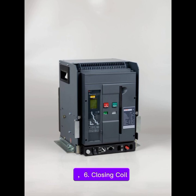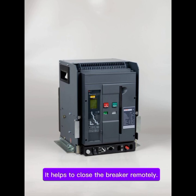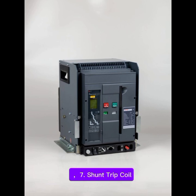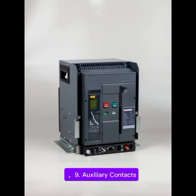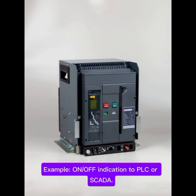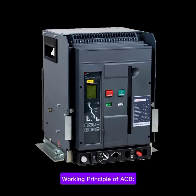6. Closing coil. It helps to close the breaker remotely. 7. Shunt trip coil, used for remote tripping. 8. Under voltage release, UV trips breaker when voltage becomes too low. 9. Auxiliary contacts, used for indication and interlocking. Example, ON, OFF indication.